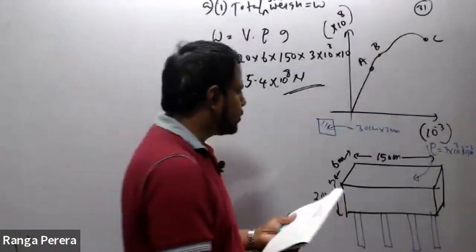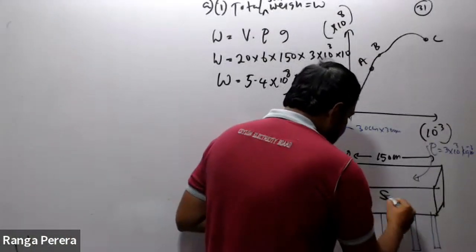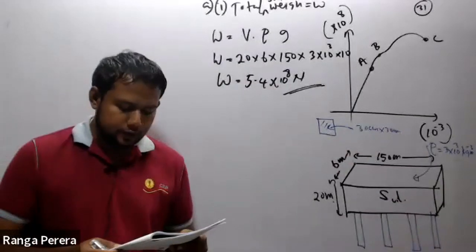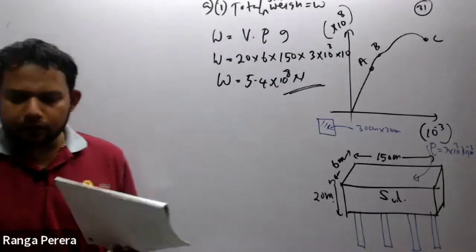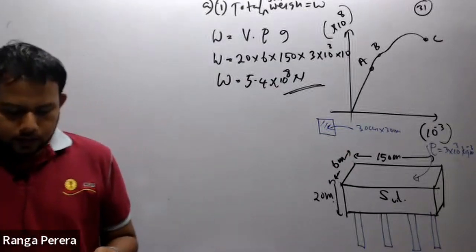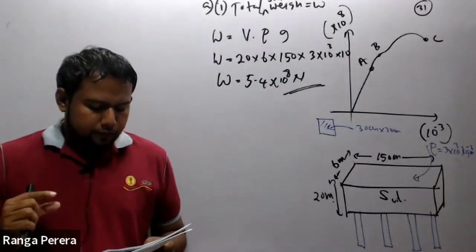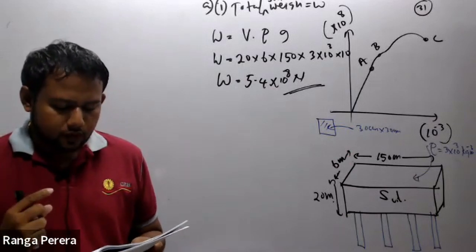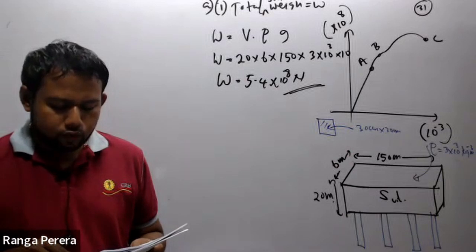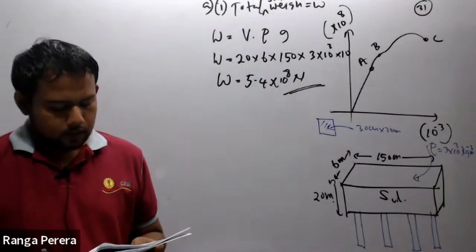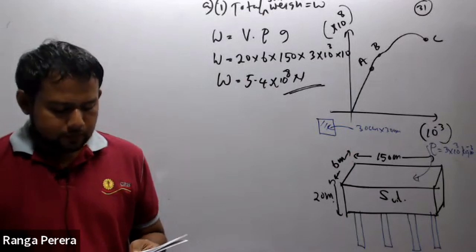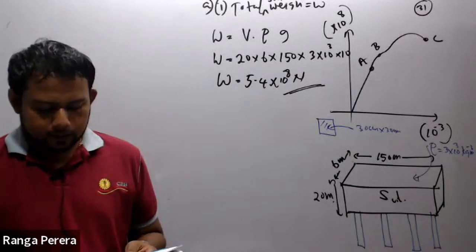Inside this, we have a soil. Even in figure number 3 and figure number 2, it is given. What is the number of columns needed to keep the compressive stress on each column at 2 × 10^8? Assume that the weight of the soil is equally distributed along the columns. Neglect the mass of the roofing material.